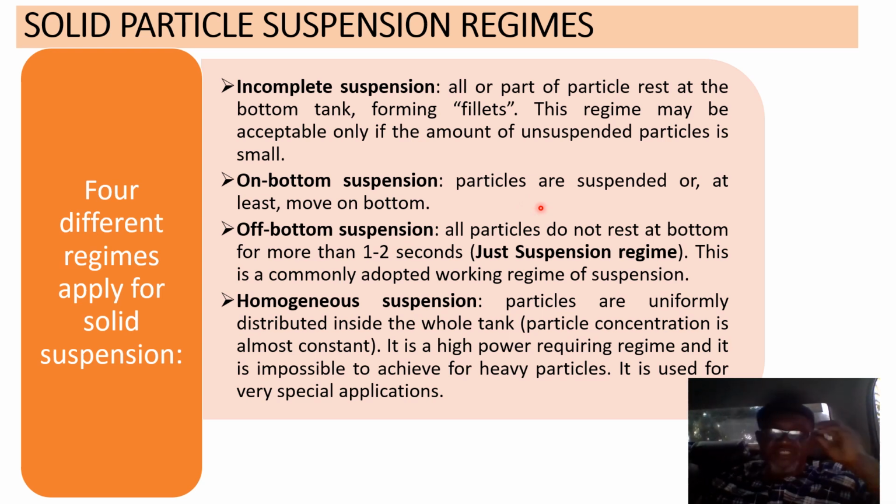Solid particle suspension regime. When you have solid particle suspension in a tank, there are basically 4 different types of regime. One is the incomplete suspension, where some of the particles will be resting at the bottom of the tank.